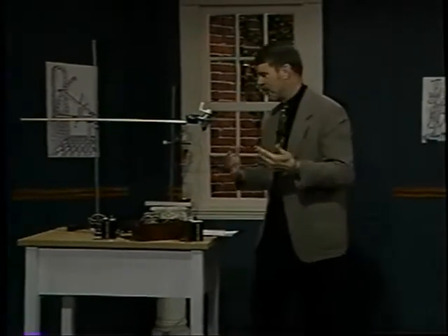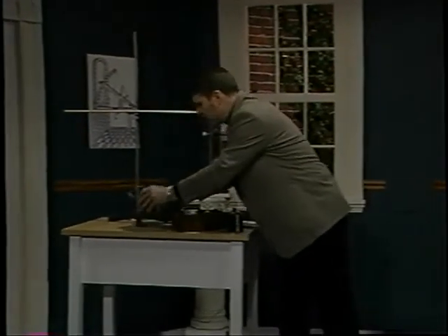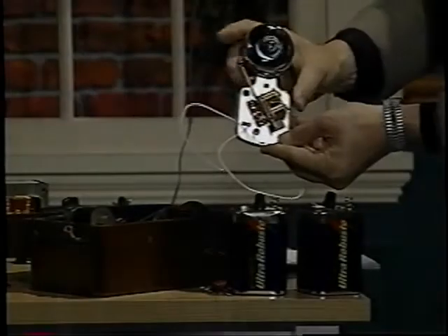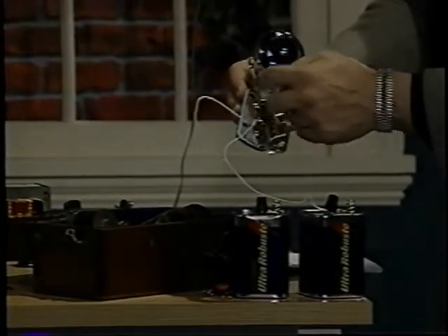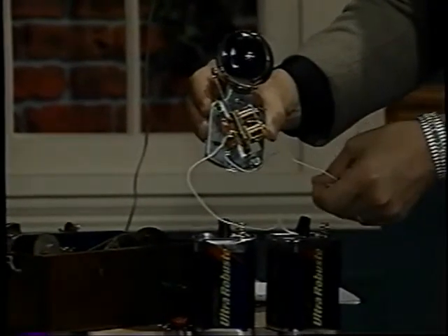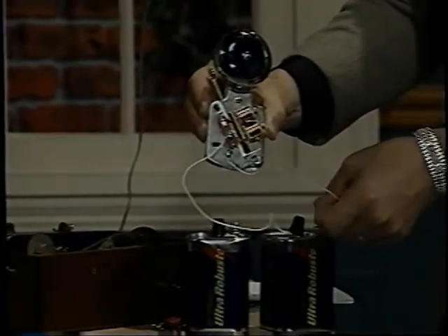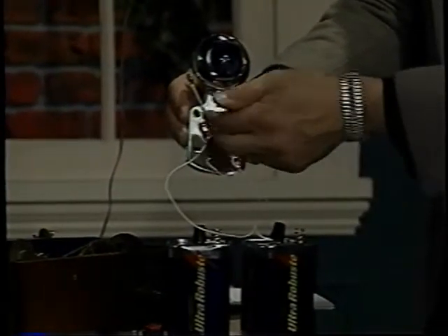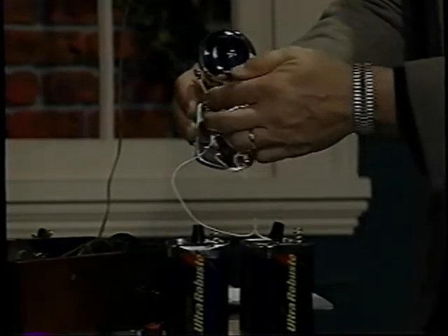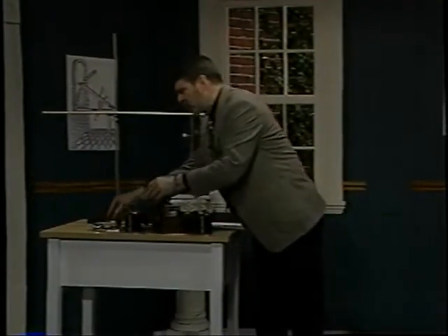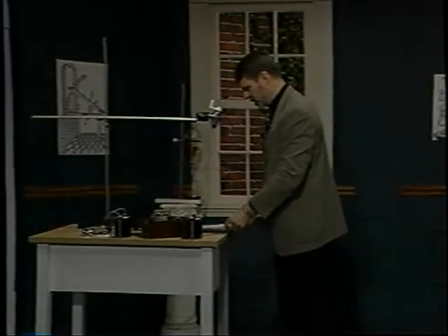You can go one step further. You can take those coils of wire and wrap them around so they create an electromagnet that attracts a clapper, a piece of metal. And therefore you can create a buzzer just by closing the circuit. Again, what you're doing is creating a magnetic field. It attracts a piece of magnetic metal which claps against the bell. So that was the principle of the buzzer and various other kinds of sound-making devices.